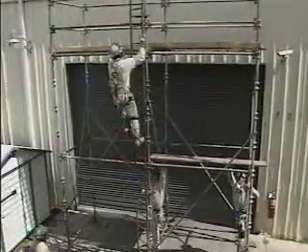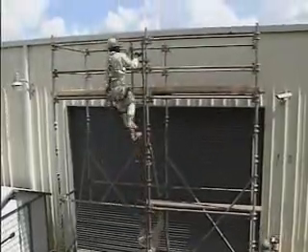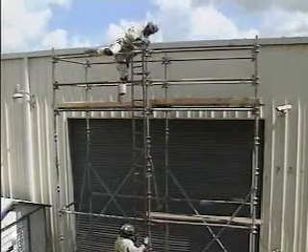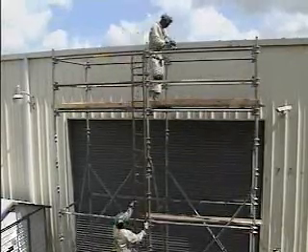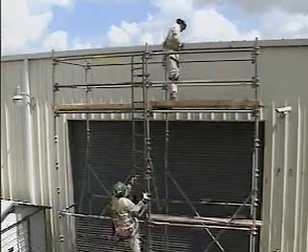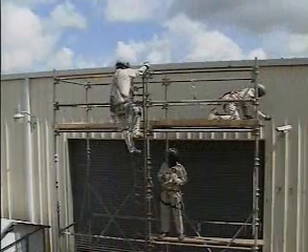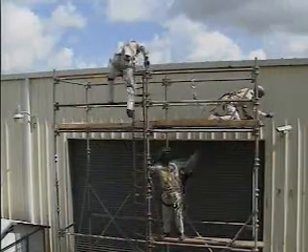For example, always use both hands when you're climbing a scaffold ladder, and be careful when you're entering or leaving the work platform. Don't jump onto the scaffold flooring, since there's always the possibility that a plank could be loose or break. Also, avoid overloading a scaffold.